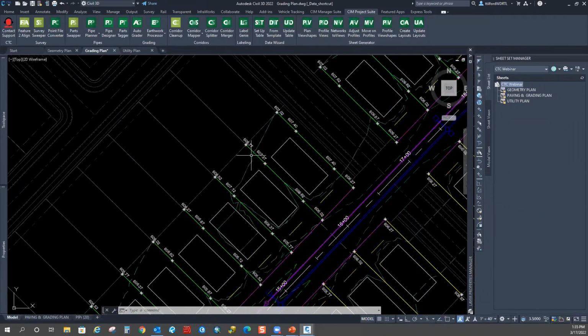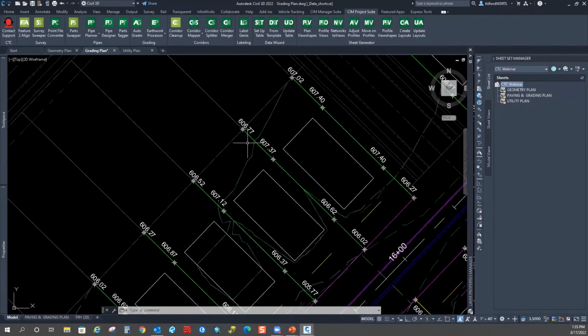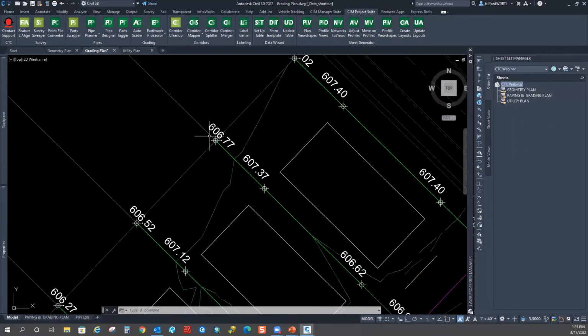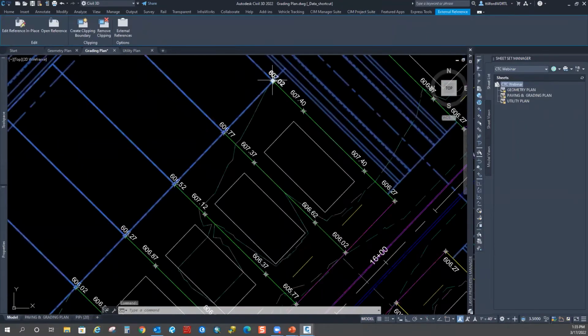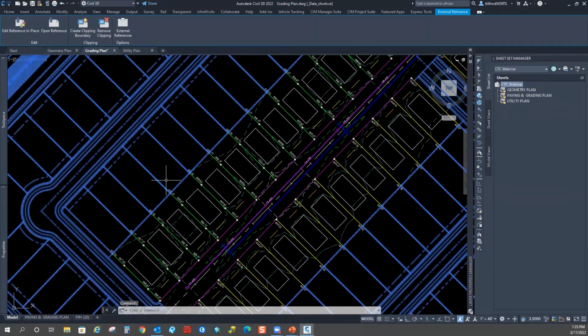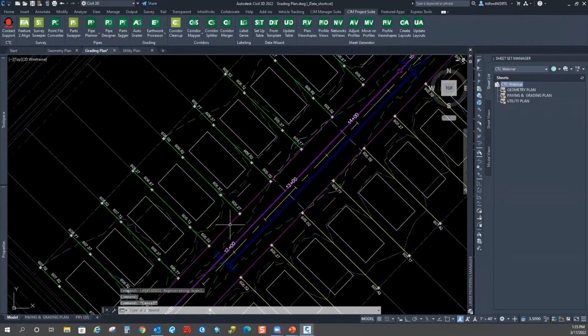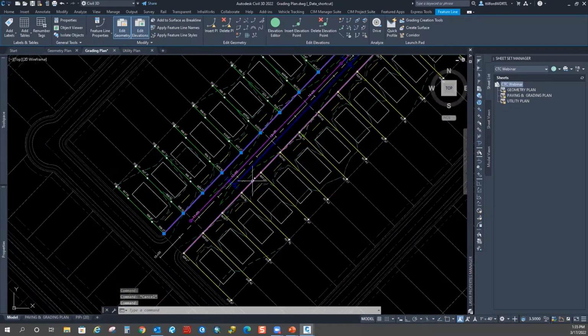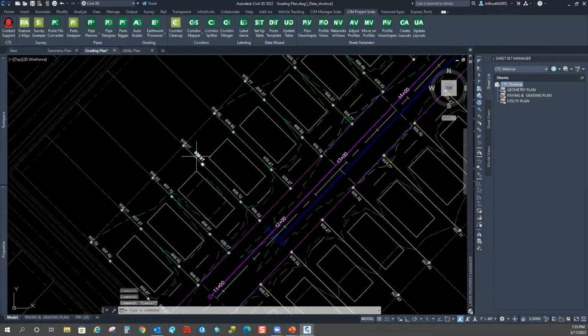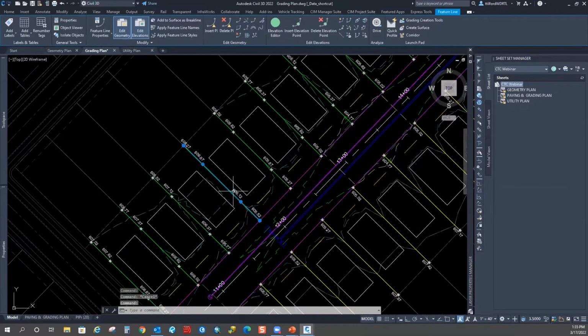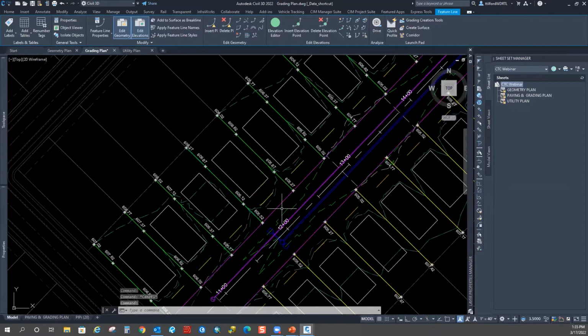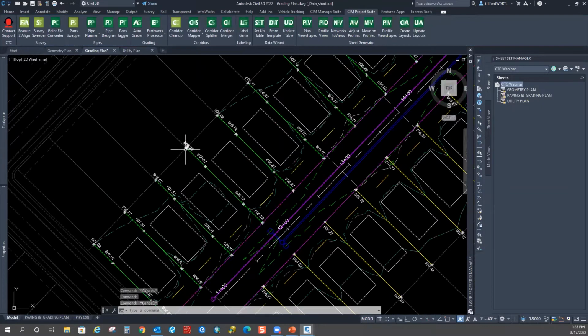All right. Now, right now I have this set to probably 2%, and it's just kicking this out for me. If this was not a 2% and it was actually tied to another feature line that was touching out here, this would have to know a little bit about your hierarchy of feature lines. So if these are actually children, a style called child, and these are on one that's above child in the site, this one back here may be existing or something.